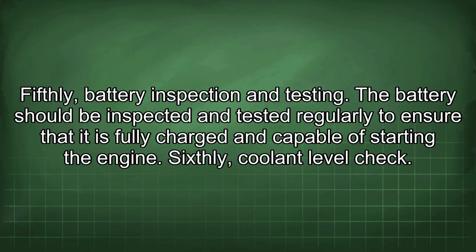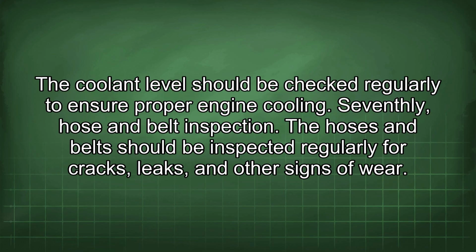Fifthly, battery inspection and testing. The battery should be inspected and tested regularly to ensure that it is fully charged and capable of starting the engine. Sixthly, coolant level check. The coolant level should be checked regularly to ensure proper engine cooling. Seventhly, hose and belt inspection. The hoses and belts should be inspected regularly for cracks, leaks, and other signs of wear.